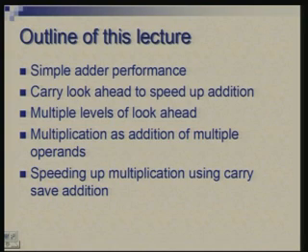The technique used there would be what is called carry save addition, where we postpone the use of carry rather than trying to immediately look for carry and wait for it. We will postpone that and add at a different stage. So, in the process we will speed up the operation.